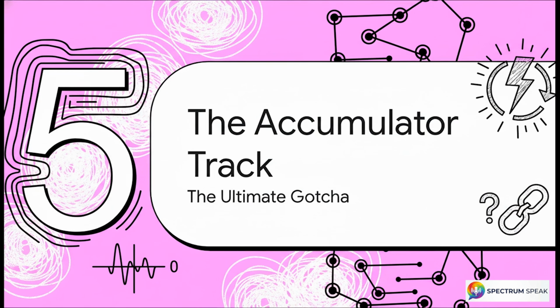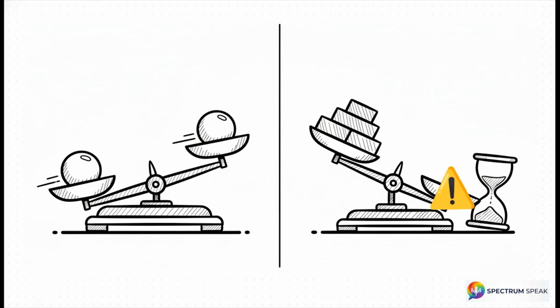Now let's talk about the gotcha, the accumulator track. Unlike those naturally balanced words that don't require you to remember anything about the past, those 10 combinations from Table 2.8 totally depend on historical context. The output for sending 0000 isn't just some static code. It dynamically changes based on exactly what happened milliseconds prior.